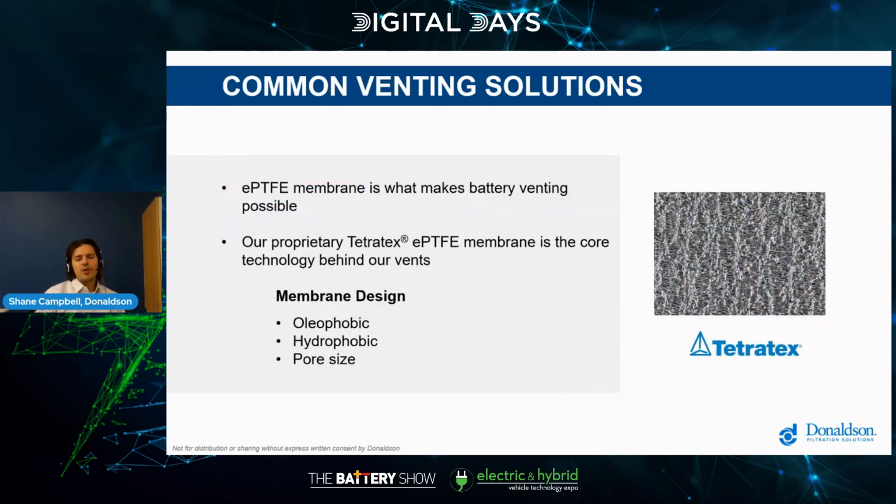The core technology that really makes all of this possible is our ePTFE membrane. At Donaldson, we developed this in-house with our proprietary Tetratex ePTFE. This membrane is oleophobic and hydrophobic. And because it's developed in-house, we are constantly looking at how we can improve this product and which formulation is best, by optimizing pore size and other membrane properties to work in a dual stage battery vent.